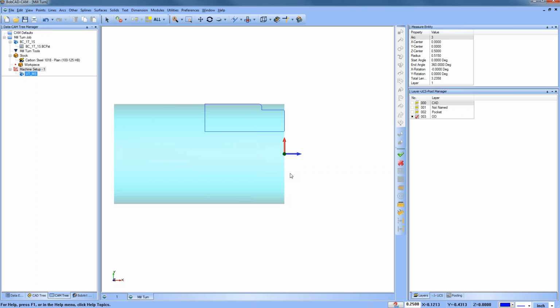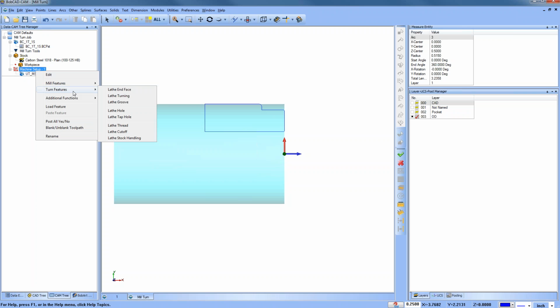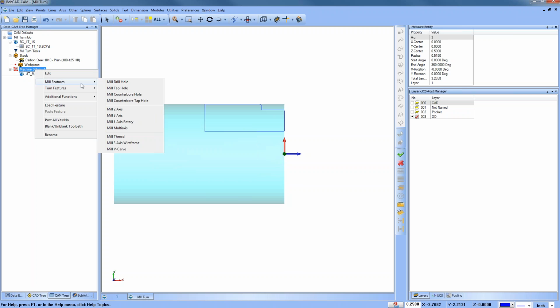That is not the case. All the turning profiles are in this same orientation, and then your machine group will tell you whether you're going to use that or not. And in our case, we have upper turret main spindle. That's all we have, so that's all we're going to use. All right. Now, I'm going to, again, we can come in here. When we get into our machine setup, you'll see both your milling routines, and then you're also going to see your turning routines as well.